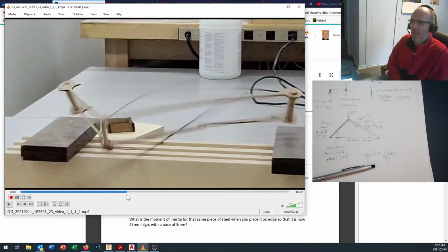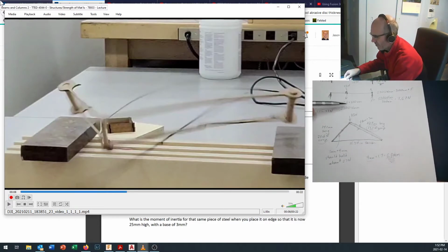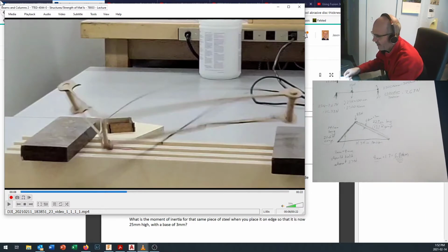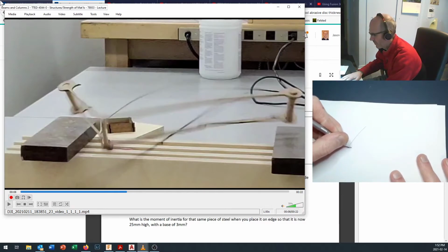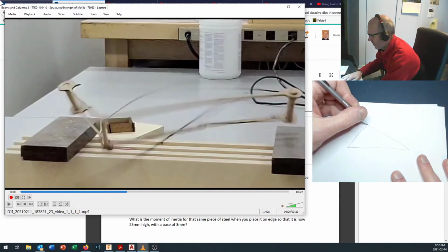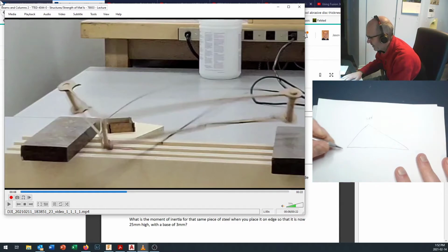So it was time to take a look at our calculations and find out a little bit about what went on. So if we had this structure and it was supporting, well, we'll say 6.8 kilos, that means that each side was supporting 3.4 kilos, or we said we'd have 34 newtons coming down on each side. Let me just grab a new sheet right here. I'll try and draw it a bit bigger because the window's a bit smaller now. So if I was getting 34 newtons coming down on an individual side, then I'd have more force coming up right in here, and I could go back and redo those calculations.